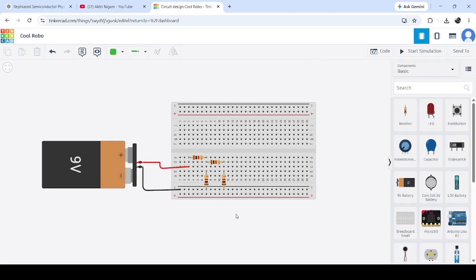Now we will follow our first step. In the first step, we need to keep our given voltage source short circuited. For this operation, firstly we will delete these two terminals and we will open our load resistance, which is given as RL.